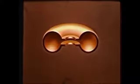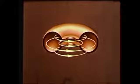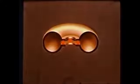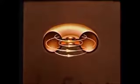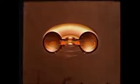This results finally in the formation of a closed resonator having certain very high resonant frequencies, which are determined by the dimensions and shape of the cavity. In a closed resonator, the magnetic field, as well as the electric field, is confined to the interior of the cavity. The associated currents and charges are to be found in a thin layer of the interior surface of the resonator.